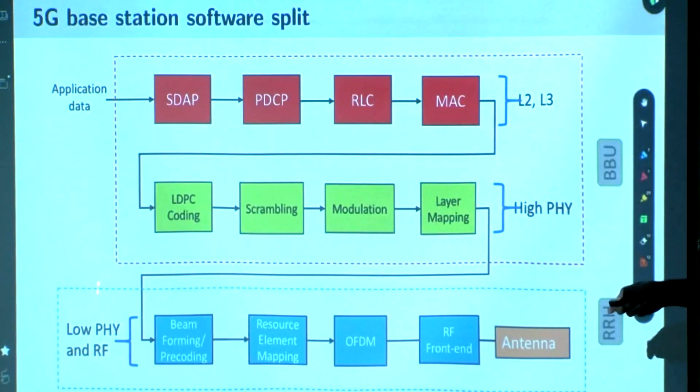And look at this, this is all still your baseband signal. Till 4G, this was also part of the same chain. Then the signal was fed to the antenna, and there are a lot of losses here. If you take the RF signal out and run a long cable, there will be a lot of losses. The digital signal has no loss, you can transmit it in the form of optical signals.